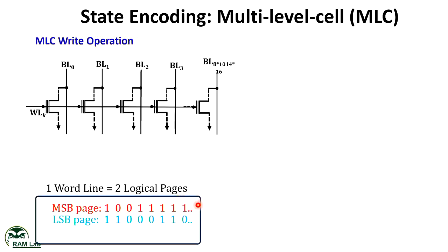So it gets the first 16 kilobyte. It knows that this will go in the LSB page. Then another 16 kilobyte, and it knows this will go to the MSB page. After that, it will decide what will be the state of each cell. So for example, what will be the first cell state? It will be L0, 1, 1. Both are erased, so it should be going to L0 state. Second one, 0, 1, goes to L1 state, 0, 0, L2 state. So from the user data, the NAND internally will find out what state the cell will be going to.